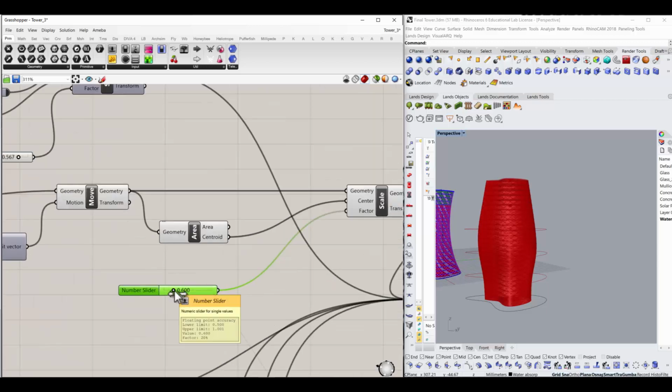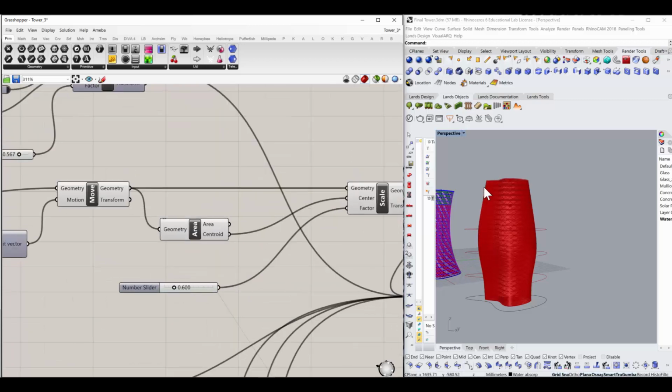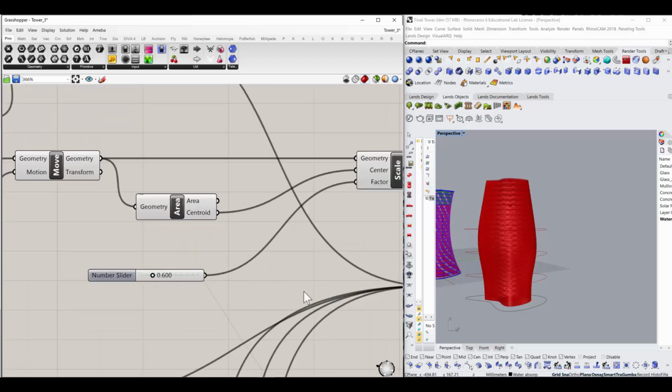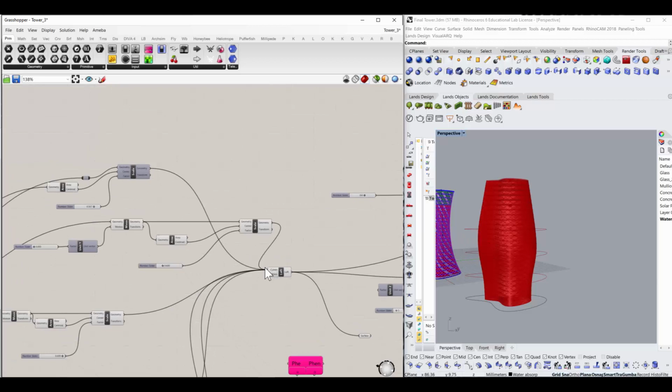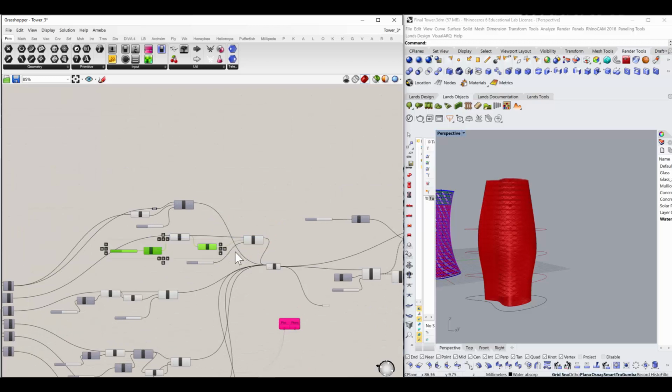This scaling changes the size of the curve. It increases the size. So I'm basically optimizing this part, so I get a form which has a different lofted shape. Because I'm scaling these individual curves, the lofted shape keeps on changing at these curves. So this is what I've tried to do here for each curve.